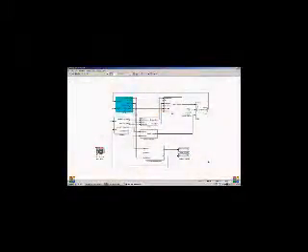This communication of sensor data and reference commands between the experimental hardware and the iOS application is made possible on Simulink because of TCP communication blocks that are available in places like MATLAB's Instrument Control Toolbox and Quanser Consulting's Quark software, which is a software that extends the capabilities of Simulink in order to run models in real time on Quanser's PC-based data acquisition and control boards.